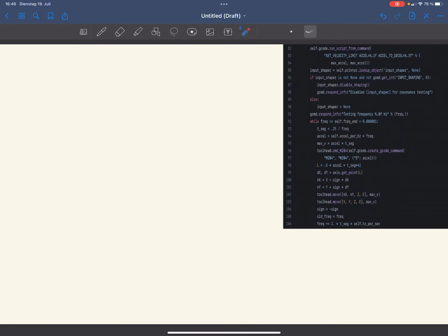So let's have a look at the code and what I think is wrong here in the mathematical or physical assumptions. So at first, what does the measurement do when we're trying to measure the frequencies, the frequency response? We are shaking the printhead at a specific frequency, and then we're measuring accelerations. And from that, we try to conclude how it reacts to those frequencies and to which it reacts the most, and where we need to dampen them, or better, it's not really dampening, it's just trying to avoid them during the movement actually. So let's start with the printhead.